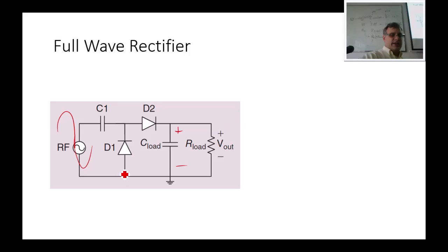Then on the minus swing, what would happen then? Well, this one then turns off, and you get positive charge that deposits on this capacitor. So then the next time when you hit the next upswing, this voltage pushes this charge through, and you get a doubling effect, right? There's already a DC voltage on this capacitor that's up to the peak of this voltage amplitude minus the turn-on voltage of the diode. And then this is sort of riding the voltage to the next level.